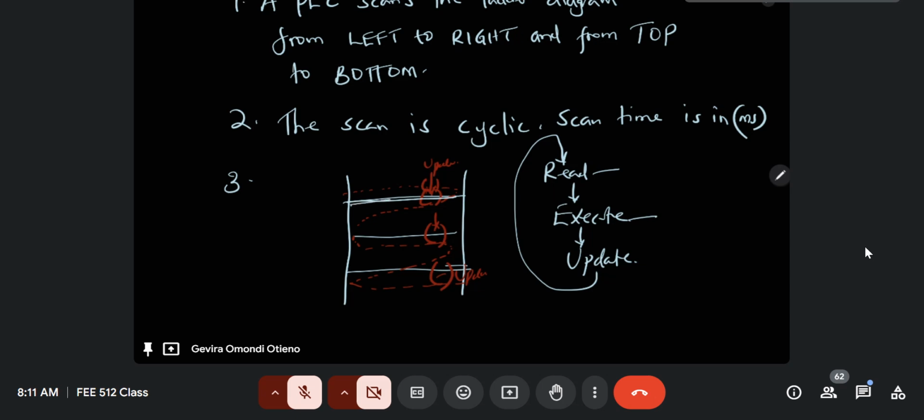So you read the rung and you execute the expression or the instruction that is there. Then you note the status of the output, but it is not updated immediately. It is just evaluated so that we know that that rung should have that state. Then the output in that rung should have a particular state. We move on because the scan cycle is not complete.